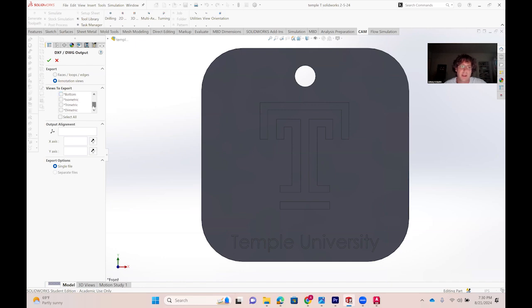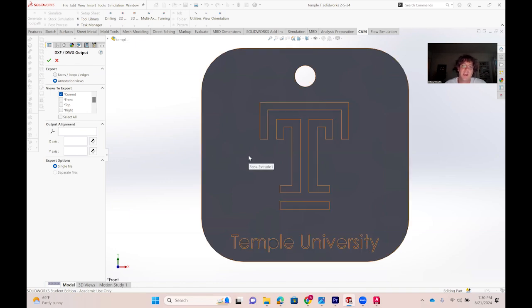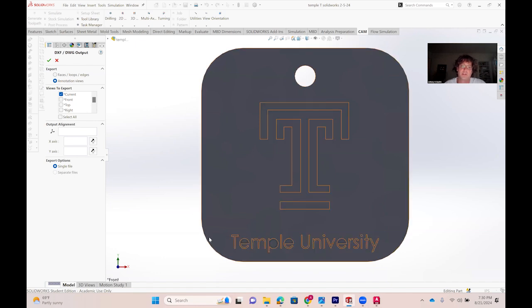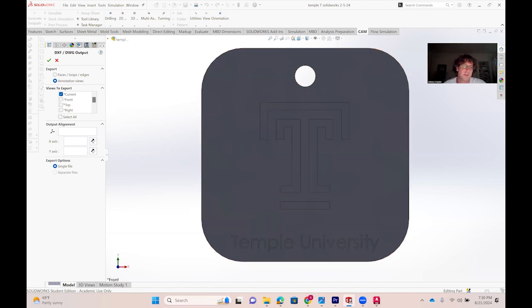A lot of times I forget what is the plane I sketch from, so usually it's just easier to do current. I could also do faces, loops, and edges, which involves selecting a face, but then I would have to go on the inside of the P and the E's and make sure all those were selected too, because it would not select them. So it's largely more work to do it any of the other ways other than what I showed you. I find that to be the smoothest method, but yeah, certain times you might need to use some of those other methods.